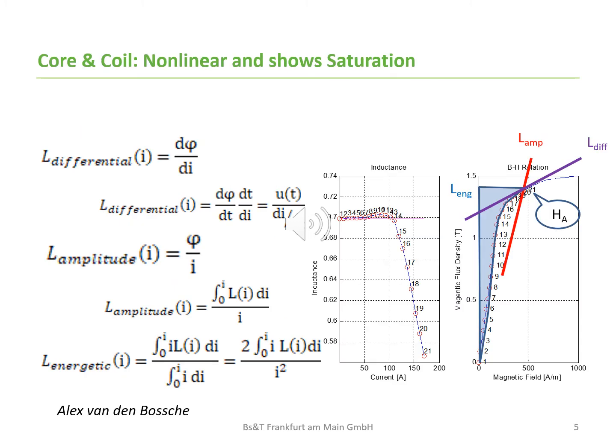Soft magnetic cores and soft magnetic components show saturation. The nonlinearity is articulated by the inductance concept. The inductance concept is a parallel concept to the permeability to describe material nonlinearity. The material nonlinearity is normally illustrated by the BH loop and BH curve, particularly for soft ferrite. The temperature influence is huge.